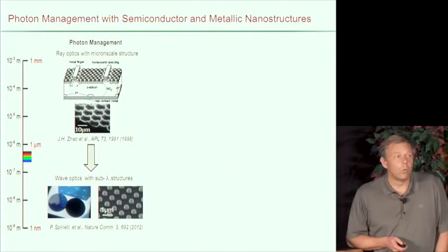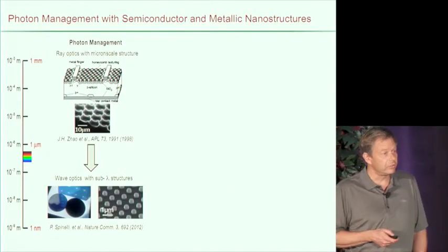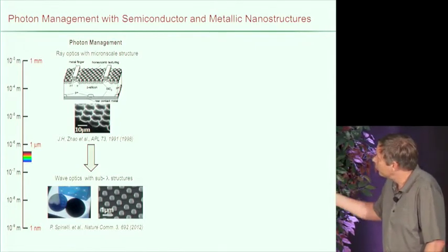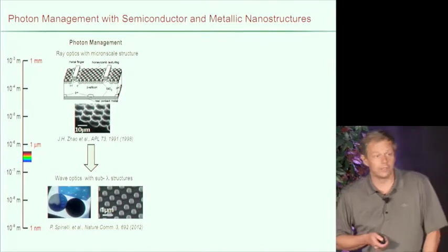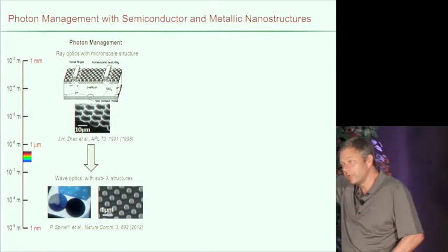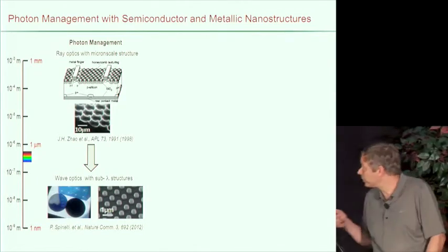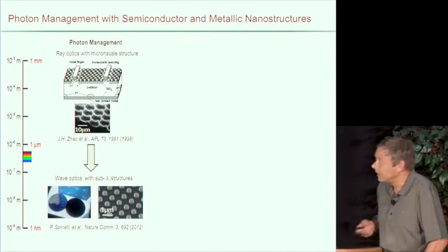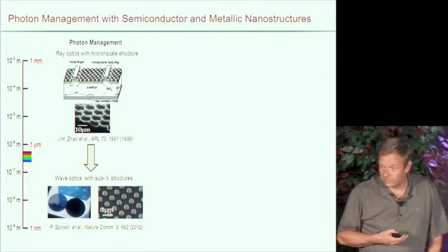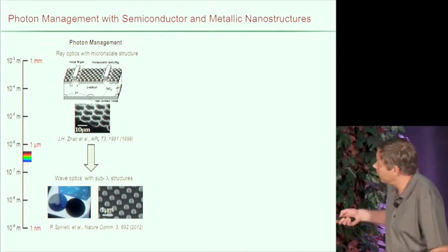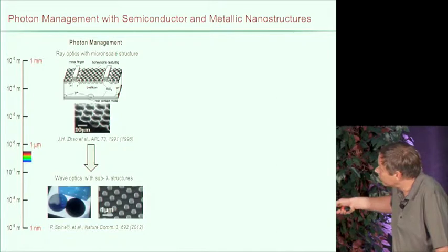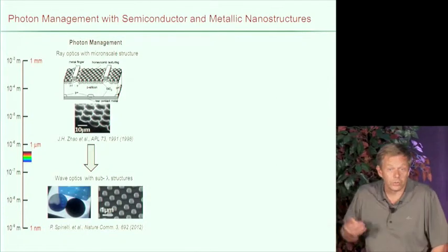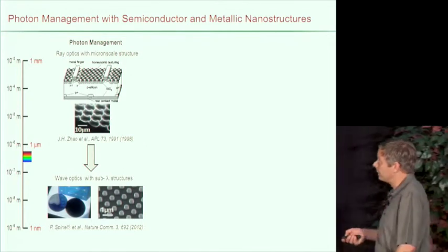So let me give you one trend in solar cell research, plotted along a length scale. We're used to, for example, beautiful crystalline silicon solar cells that had textures that were many wavelengths in size. Here's one with a 10-micron scale bar to try and trap light in many hundreds of micron crystalline silicon solar cells. We're now trying to go to extremely thin solar cells, where the thicknesses are maybe just on the order of 10 microns, or perhaps even thinner.